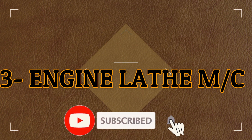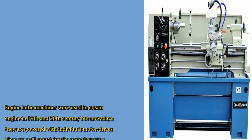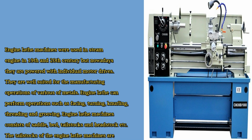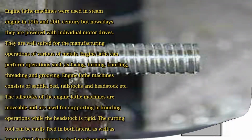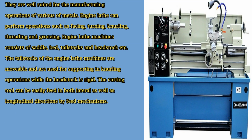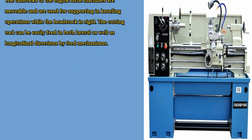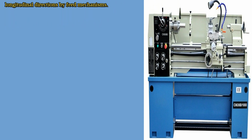3. Engine lathe machine. Engine lathe machines were used in steam engines in the 19th and 20th century but nowadays they are powered with individual motor drives. They are well suited for the manufacturing operations of various metals. Engine lathe can perform operations such as facing, turning, knurling, threading and grooving. Engine lathe machines consist of saddle, bed, tailstock and headstock etc. The tailstock of the engine lathe machine is movable and is used for supporting and knurling operations while the headstock is rigid. The cutting tool can be easily fed in both lateral as well as longitudinal directions by feed mechanisms.